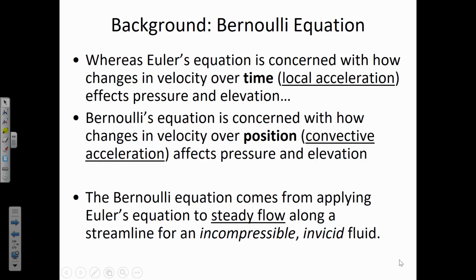The other is that we apply it along a streamline. Now consider the types of cases that we're actually going to apply Bernoulli's equation to. Remember that when we worked with convective acceleration before, we had some sort of a nozzle where the velocity was increasing because flow was going through a converging section.